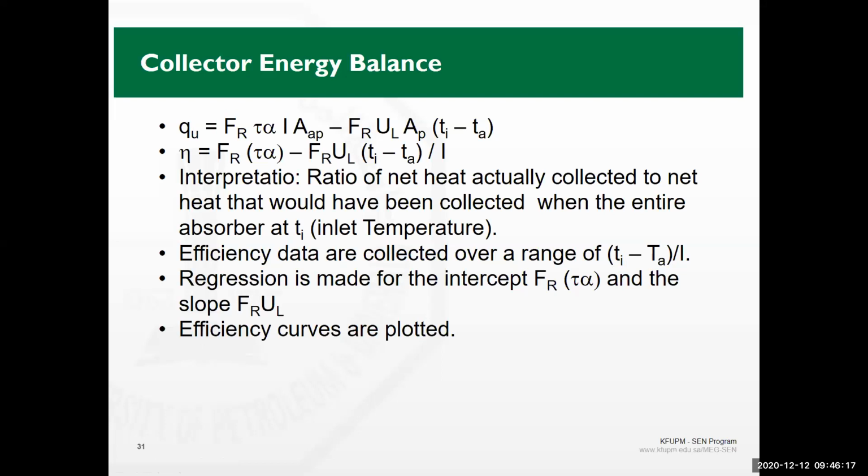And then this is going to be curve fitted using regression, whether it is given in a linear or a quadratic relation. And you will find that every manufacturer who is producing solar collectors should provide a specification sheet, and in the specification sheets, it should give these values, which are the FR.